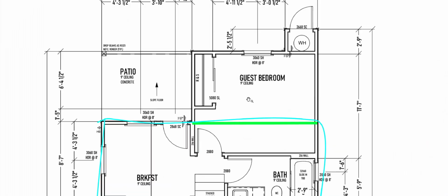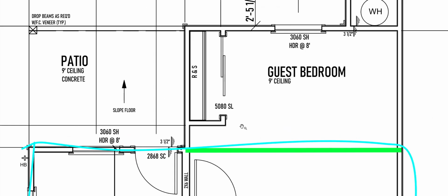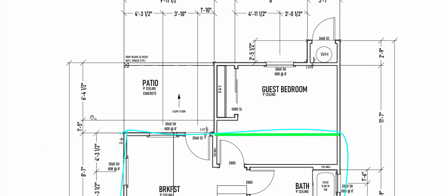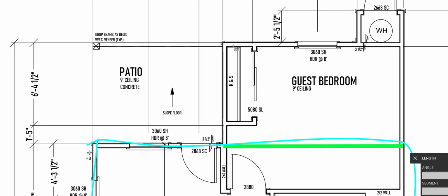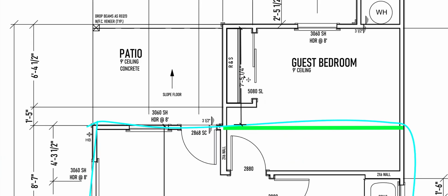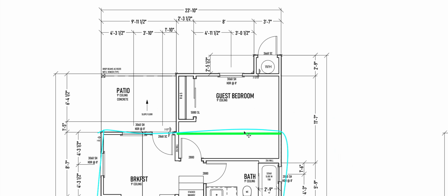Okay. What about the back of the house? Well, my rafters are going to start on the wall. They're going to slope down and land on this wall. So what's that span? There's no dimension on here that's telling me really. So let me just grab this tool. 7'5". Okay, so I'm fine. I can go 11 feet with those 2x6s, so I got plenty. So I'm just going to put my 2x6s in, and everything's all going to be fine.